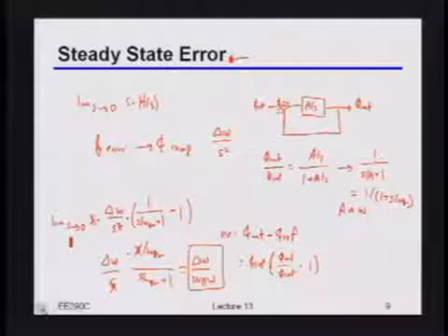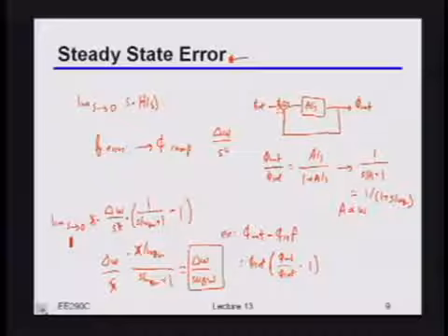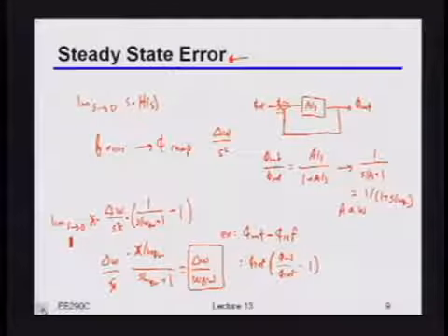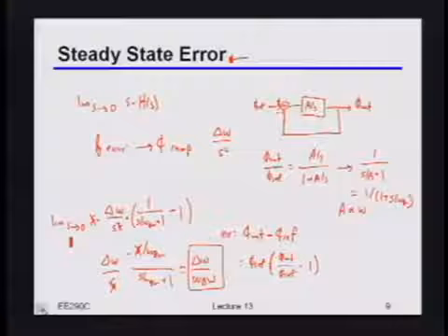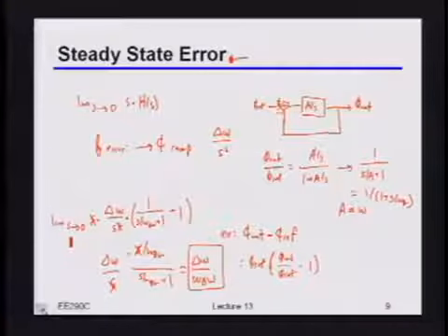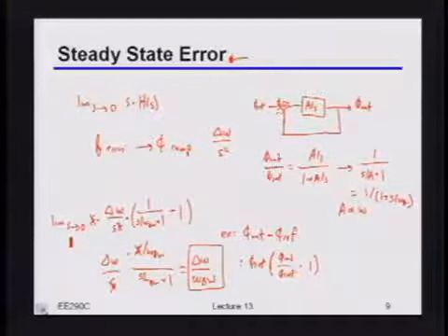Okay, so just to come back to here, we said that if we really did have this plesiochronous system with that CDR that I drew before, then we had this bad trade-off between how fast we can track those ramps, and therefore how much static phase error we are going to get, versus how much we can filter out the ISI jitter. Okay? So what do you guys think we're going to do? How are we going to fix this problem? We have the same problem in a PLL, so put one more. Yeah, there we go. Exactly.